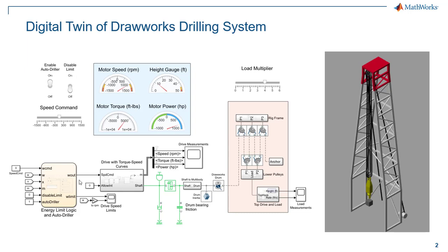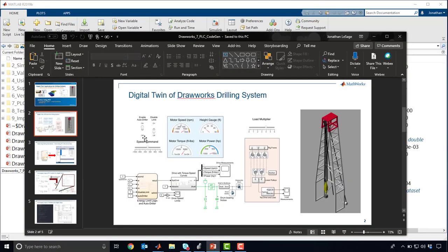We're actually going to take this Stateflow chart and convert it over to structured text that can be used on a PLC. We could just as easily convert this over to embedded C code and take that to PLCs that support compiled C code or to other platforms as well. So let's hop over to Simulink.